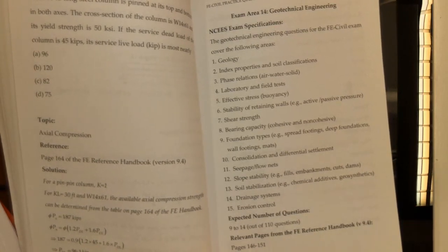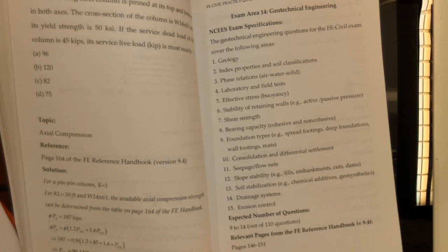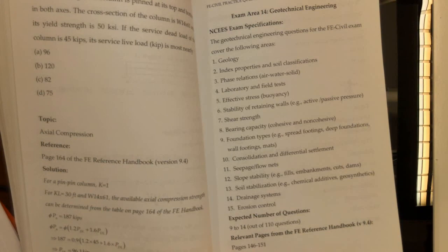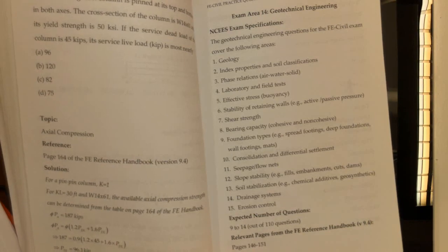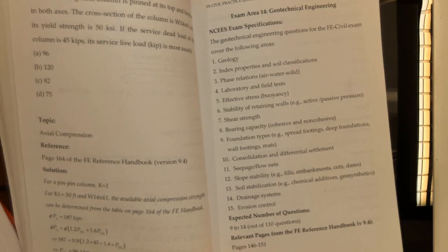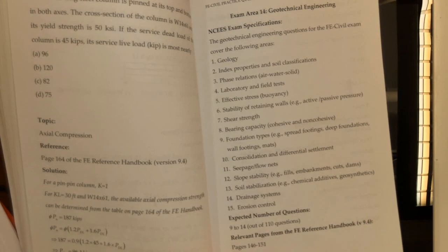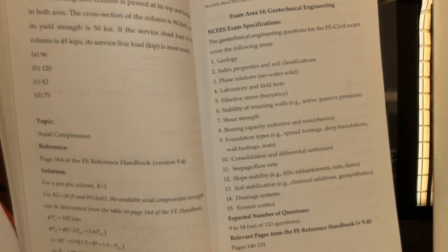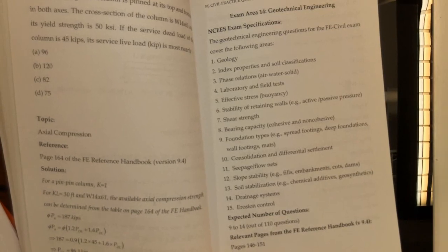The bearing capacity, again, I think what we see in the reference manual is ultimate bearing capacity, calculate an equation for ultimate bearing capacity. They're going to have to give you the coefficients to use for those calculations, and in the case of the one example that we looked at, some of them are going to be 0, so that should simplify fairly quickly.